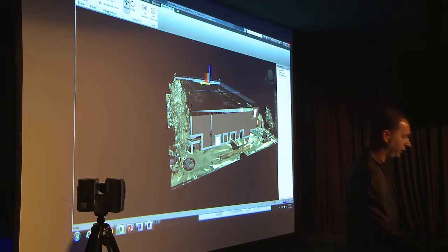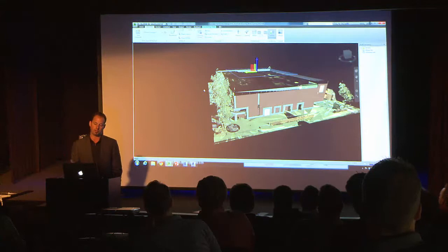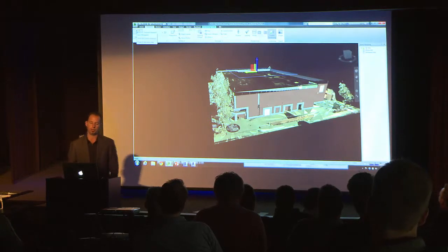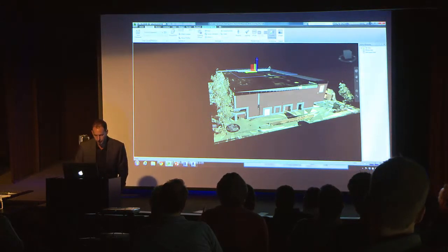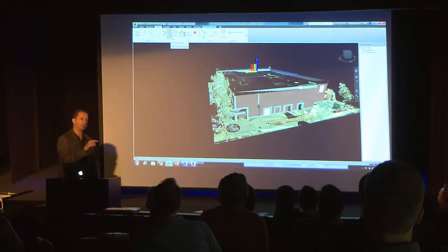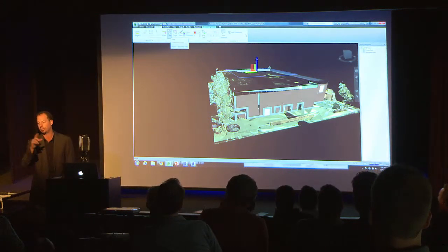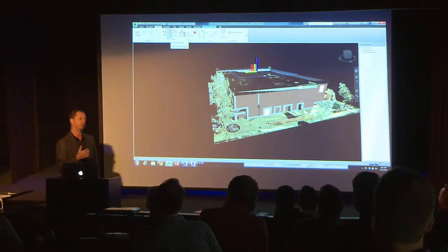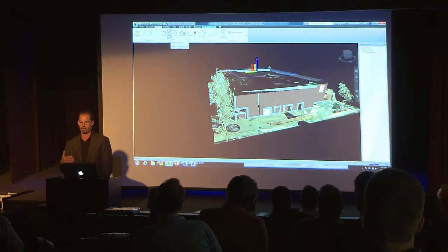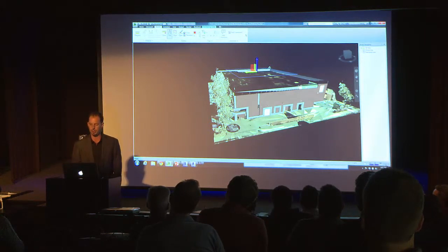We can do review. So we could have someone else open this up with a free viewer, which is to help share this data. You can go in and you can create viewpoints. We could save this. You can actually even mark this up for review. So you can put text in here. You could draw revision clouds. You could say, hey, you forgot the MEP. There's a clash here. If you have Navisworks Manager, you can do clash detection. So if the point cloud is going across the structural steel, or if you want to do verifications, you can also do any type of animations in here as well.